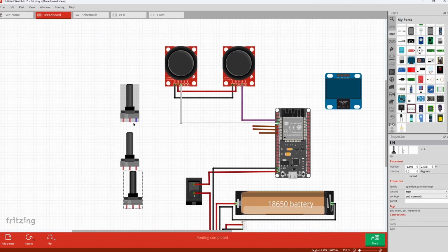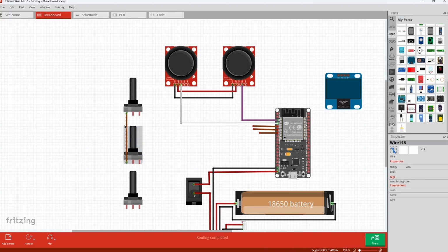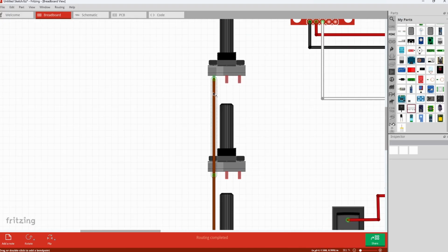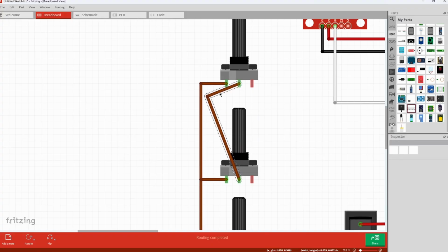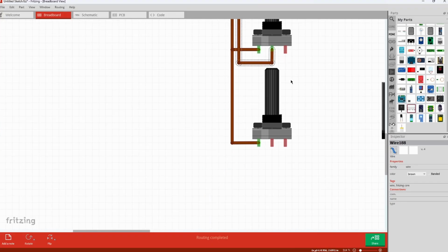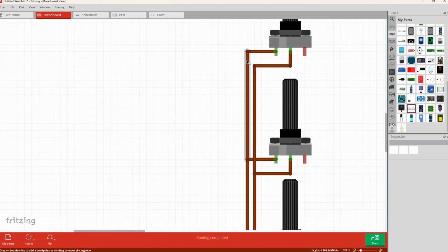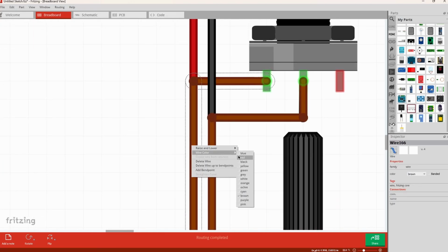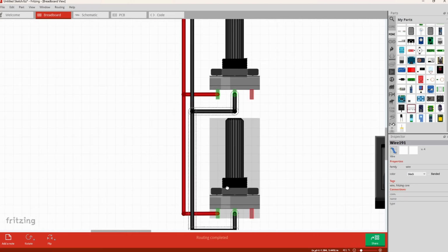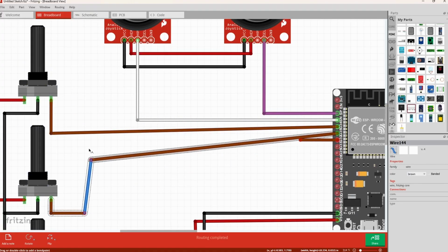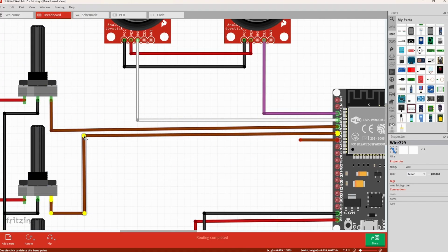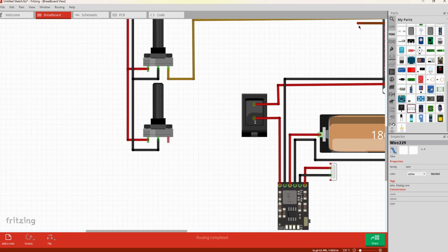That now leaves me room to connect the remaining potentiometers, which are 3, each of them requiring 1 ADC pin to themselves. So easily you can search this up, you can check the pins, you can check how to use them for the ESP32. After doing that, all I need to do now is set up the potentiometers and then wire them to 5V or generally, GND, and then wire their individual analog output pins to the analog pins on the ESP32.